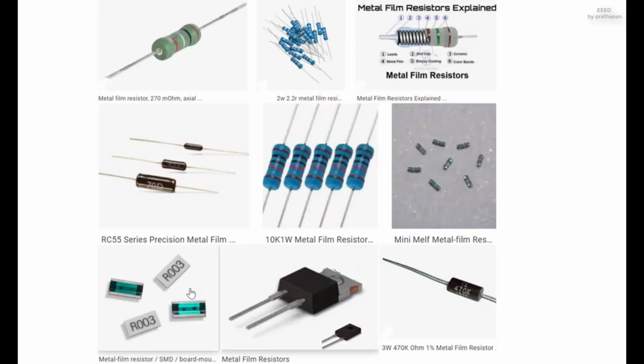Metal film. A common type of axial leaded resistor today is the metal film resistor. Metal electrode leadless face, MELF, resistors often use the same technology. Metal film resistors are usually coated with nickel chromium, NiCr, but might be coated with any of the cermet materials listed above for thin film resistors. Unlike thin film resistors, the material may be applied using different techniques than sputtering, though this is one of the techniques. Also, unlike thin film resistors, the resistance value is determined by cutting a helix through the coating rather than by etching. This is similar to the way carbon resistors are made.